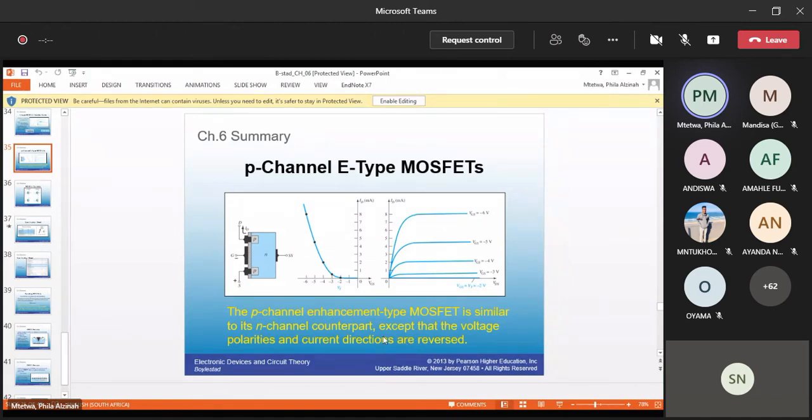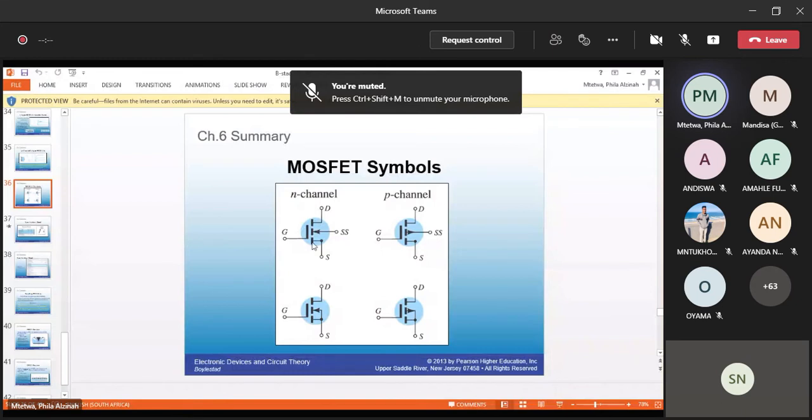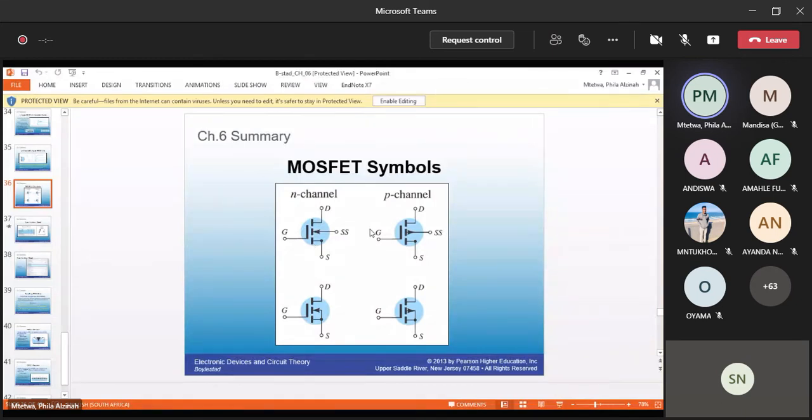And then that's a MOSFET symbol. Can you see now? It doesn't have a continuous line there, like is the case for your depletion type MOSFET. Instead, it's broken. With your arrow going in, that's your N-channel enhancement mode MOSFET. Arrow coming out, that's your P-channel enhancement mode MOSFET. Don't worry about the specification sheet and electrical characteristics.